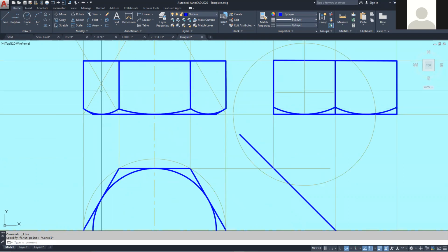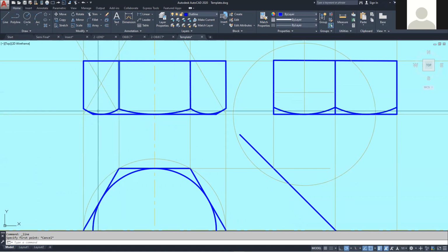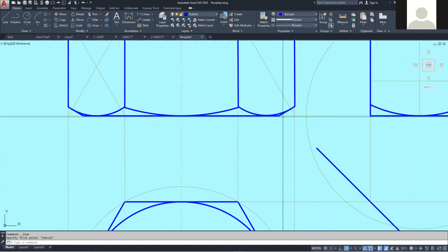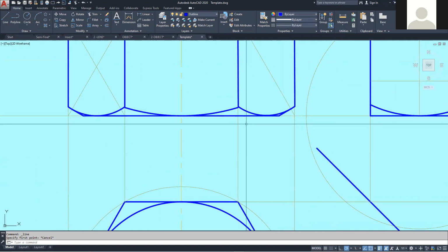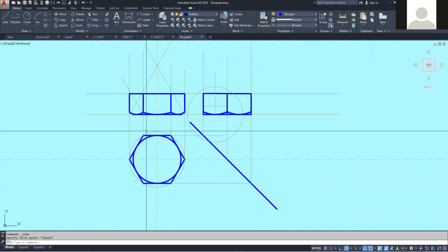And to get the smaller curve, from this corner here, you go 60 degrees again, draw this curve here. Where it meets here, you come 30 degrees. From here, you come 30 degrees and you join from here to here to get our view that will show 3 sides.